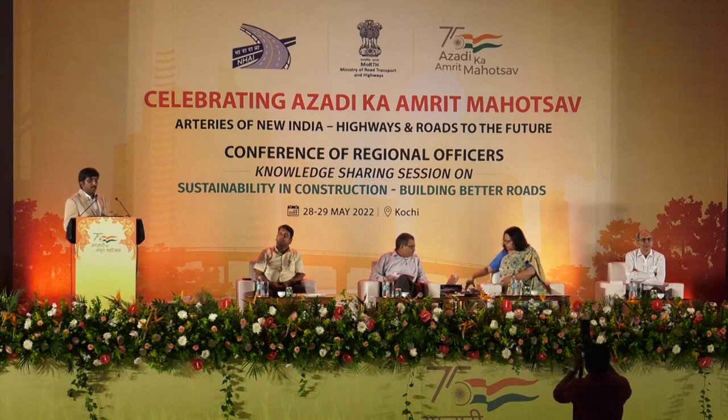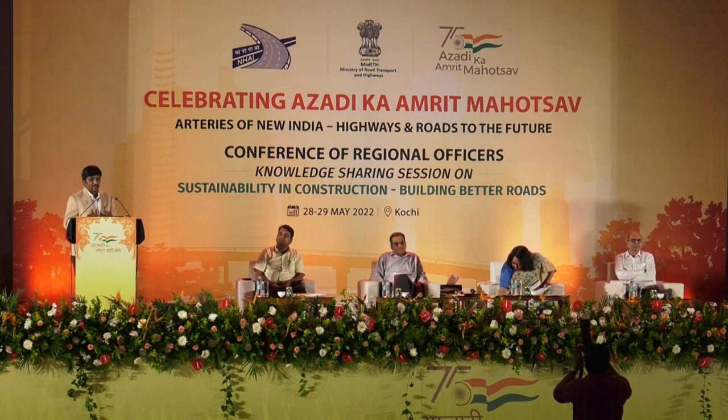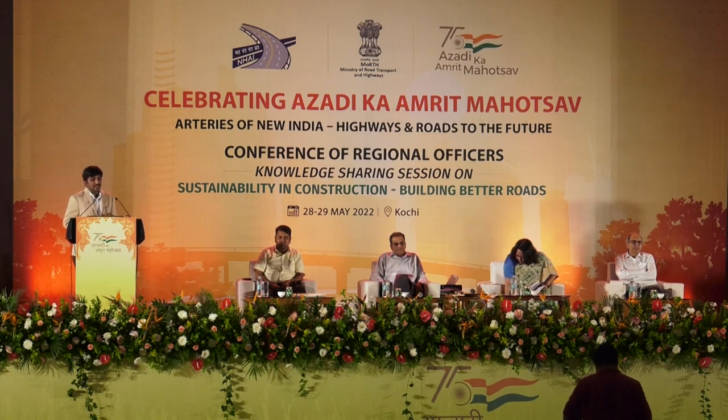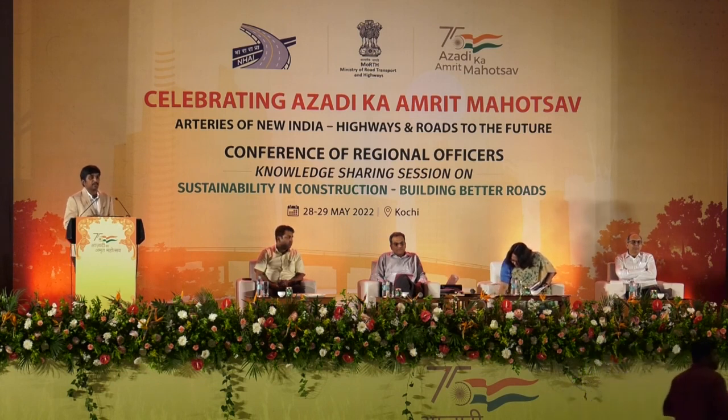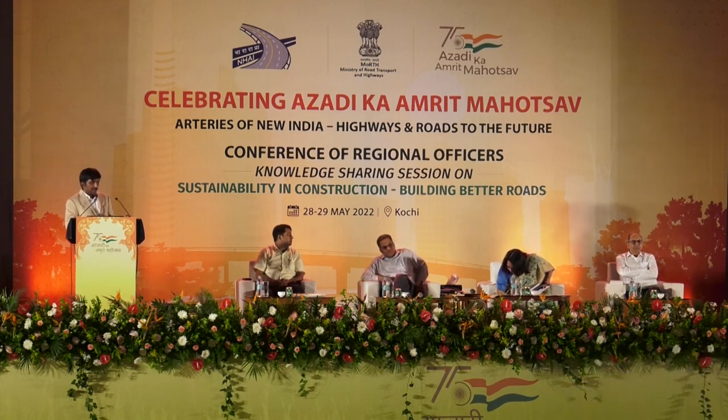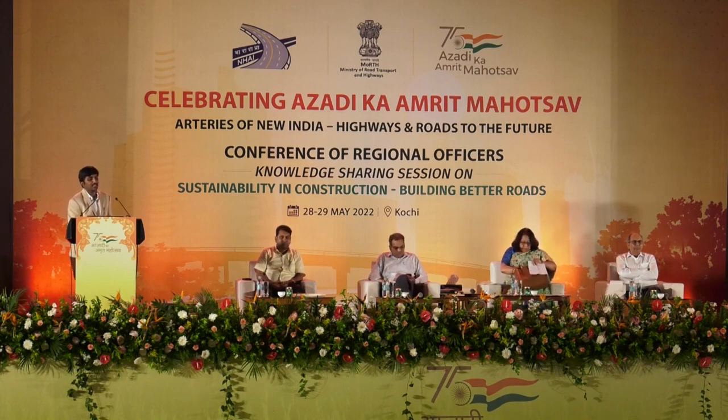Similarly, we observed other pavements also. Here they stabilized the soil layer, here they stabilized the asphalt layer. In the asphalt layer also, if they are targeting very high UCS values, you are going to find such types of shrinkage full depth cracks. So you have to be very careful while doing the mix design.